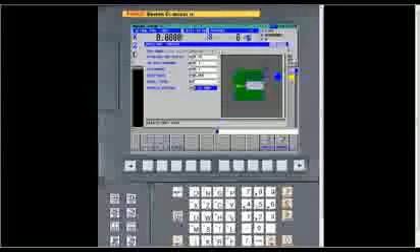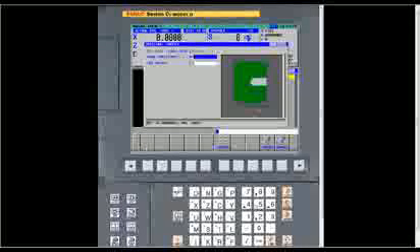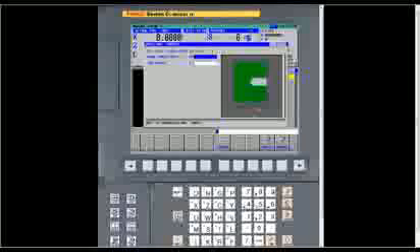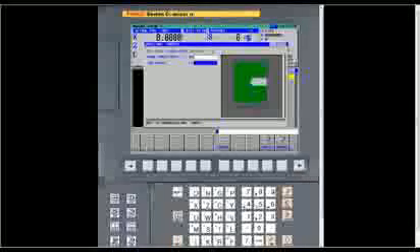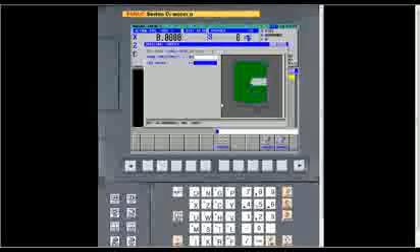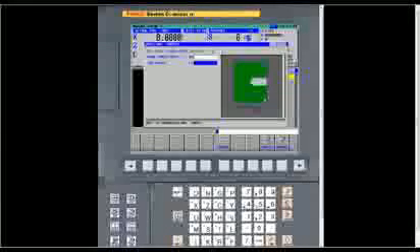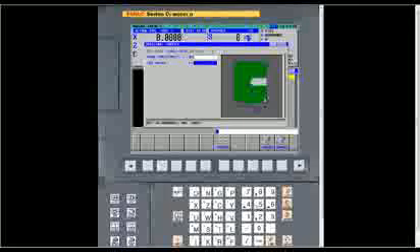To go to the next tab, we just use our arrow key. Then it asks for a base position in Z. That's just asking what the front of the part is. Then the next one is your cut depth. As you can see from the screen, you have a minus or a plus. It needs to have either a minus or a plus there.